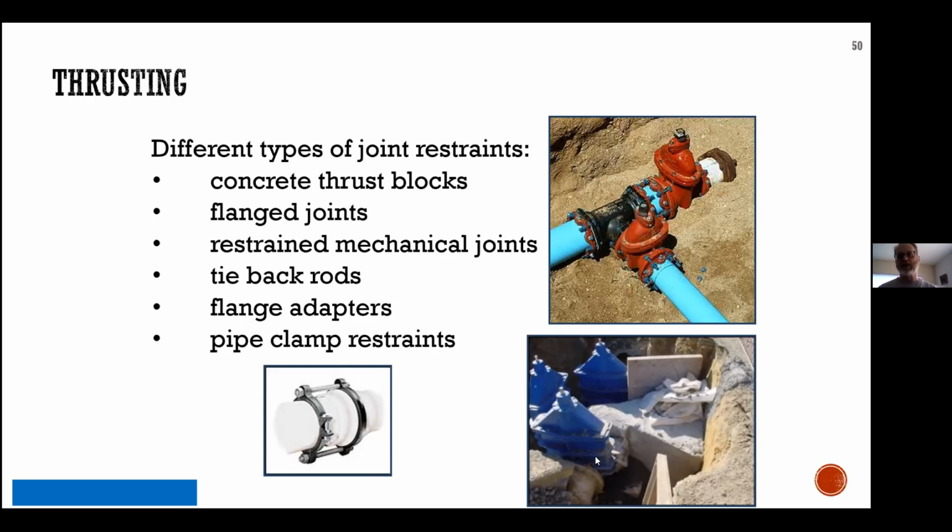This is a T, so the water is moving north-south from bottom to top and then turns from right to left. And this thrust block is meant to compensate for the actual change in direction. And that will be quantifiable. It could be an extra 2,000 pounds that needs to be compensated. And the soil itself might have some factor, but the condition of the soil, if it's wet or very loose, needs more stabilization between the pipe and the bank.